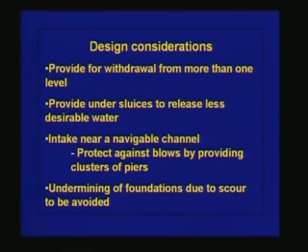It is very similar to the design of bridge piers. The foundation level for the bridge piers should go below the maximum scour that is expected during the high floods. The same principle should be used for finding out what the foundation level should be: find the maximum scour level, and the foundation level should be below this maximum scour level that can come during high floods, and that is very important. Otherwise the intake structure can get washed away very easily during high floods.